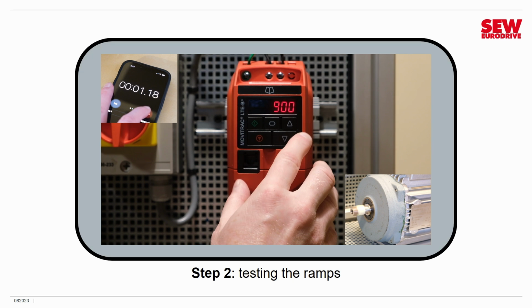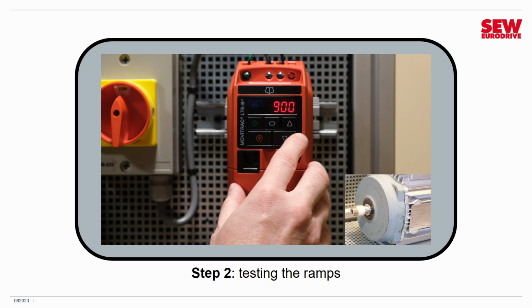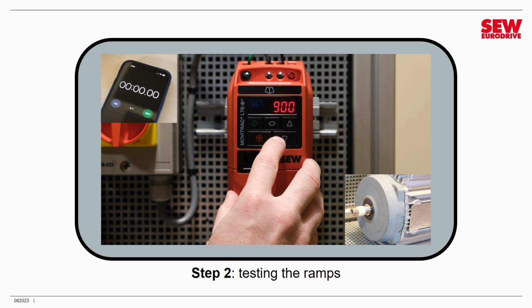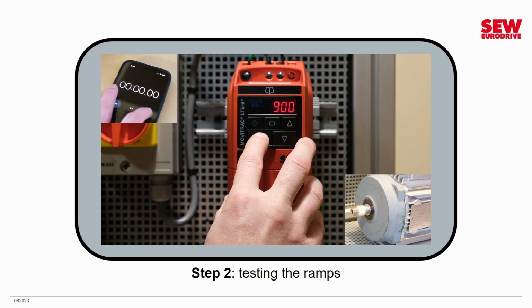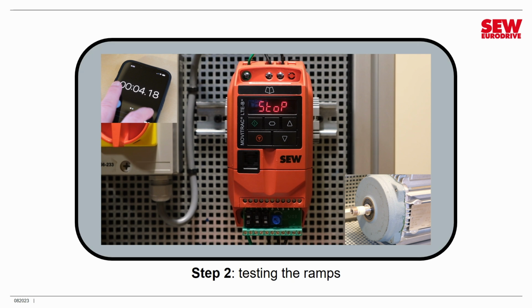Our drive is accelerating, and you can see it got up to speed pretty quickly. After all, it's supposed to happen in 1 second. And my time worked out fine, so I'm going to reset my stopwatch, and I'm going to hit the stop button and start the stopwatch at the same time. And we'll check the down ramp. Let's do that. Okay, and now we're coming down. And that took about 4 seconds. So it looks like we have been successful.